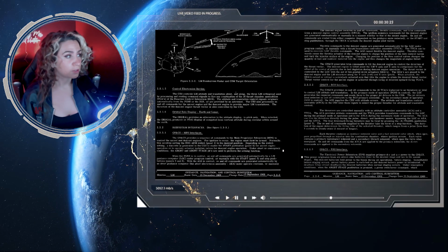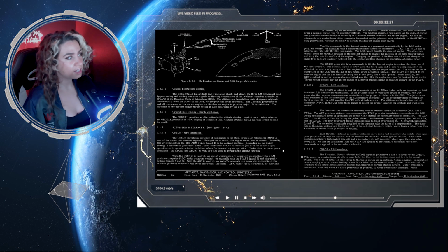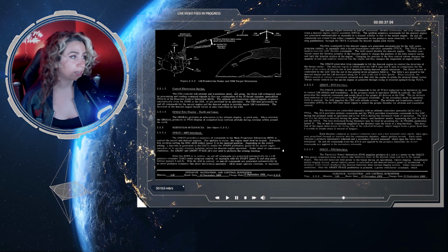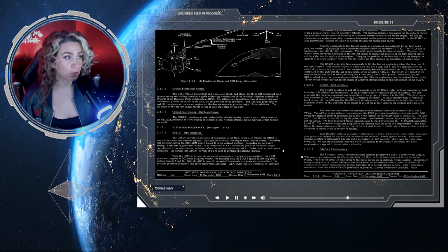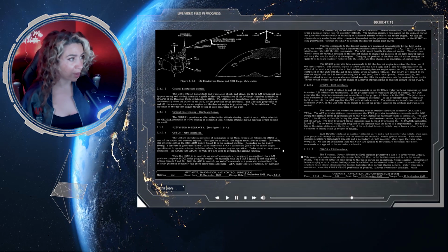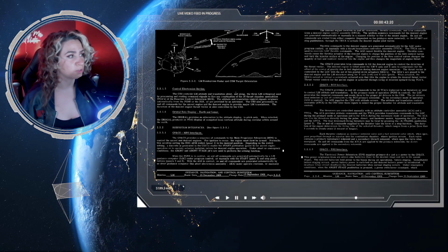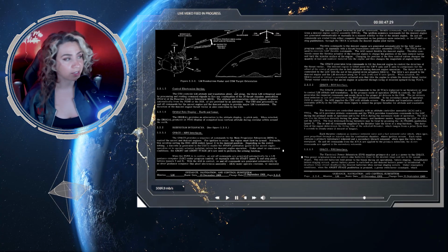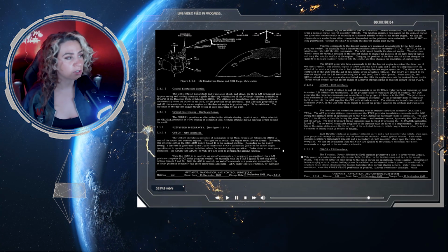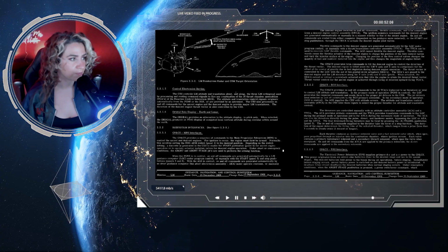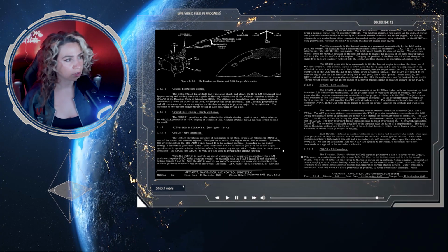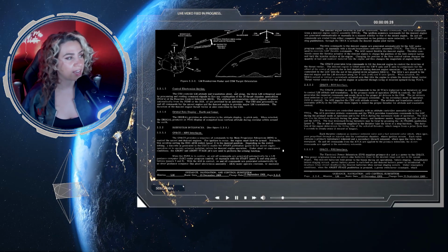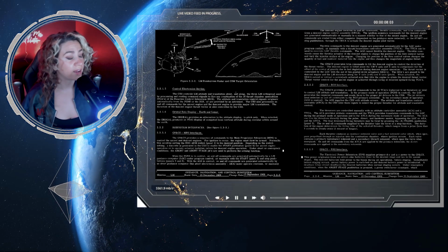Alright, let's talk about the control electronics section. The CES controls LM attitude and translation about and along the 3 LM orthogonal axes by processing and routing command signals to fire any combination of the 16 thrust chamber assemblies, the TCAs, of the reaction control subsystem, RCS. The attitude and translation control signals originate automatically from the PGNS or the AGS, or are provided by an astronaut.